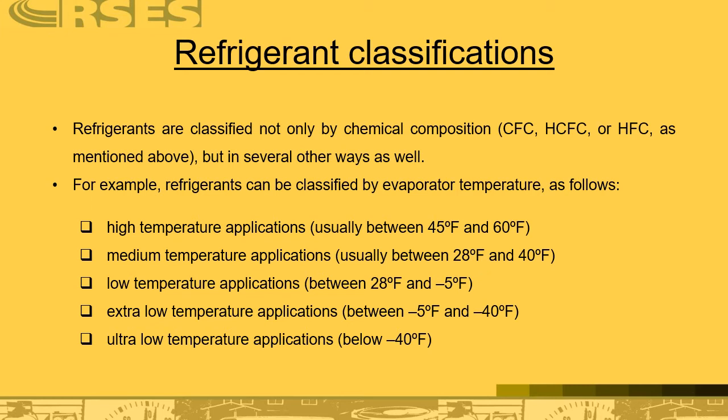Now, why would you have something that cold? I would give you an example. I was in the U.S. Navy, and one of the things we had on our ship was what we called an O2 N2 plant. It utilized R22 as a refrigerant. That particular plant basically had the ability to bottle nitrogen for us as a ship. By taking it to a critically low temperature, we could separate the oxygen from the nitrogen and bottle it for use on the ship when we were deployed.